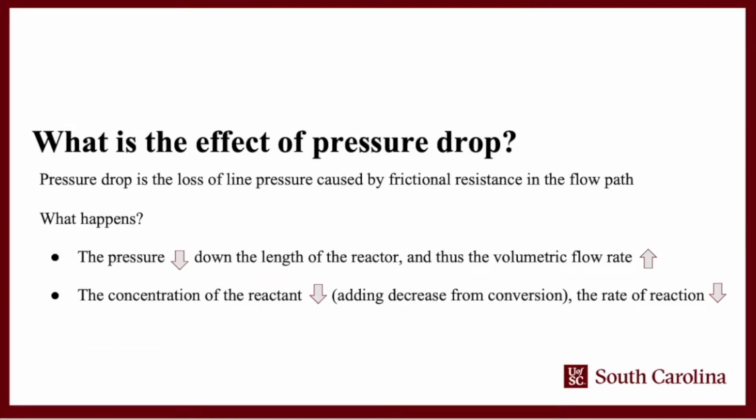And so to understand the effect of pressure drop, we first have to understand what exactly is pressure drop. Pressure drop is a term used to characterize the reduction in air pressure from the compressor discharge to the actual point of use. So pressure drop occurs as the compressed air travels through the treatment and distribution system.